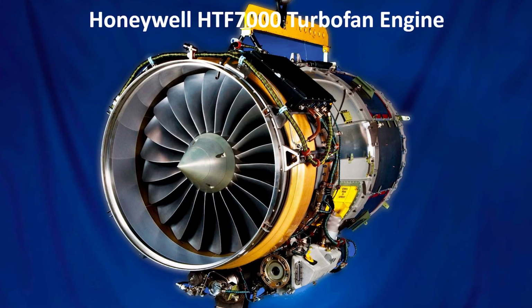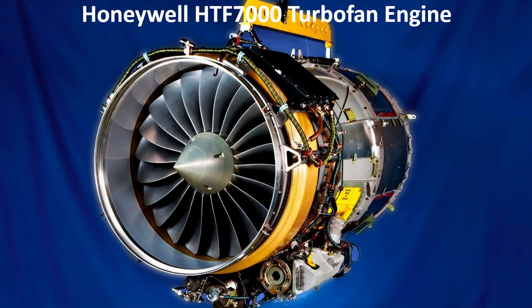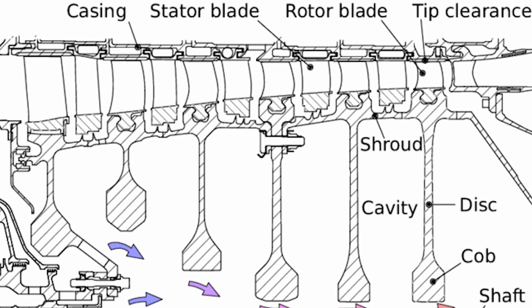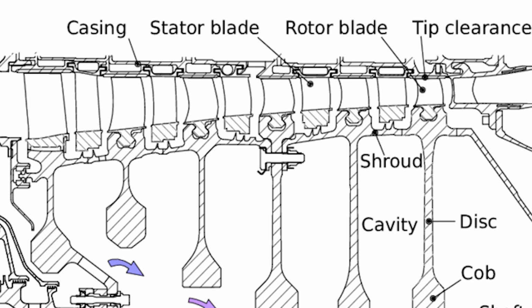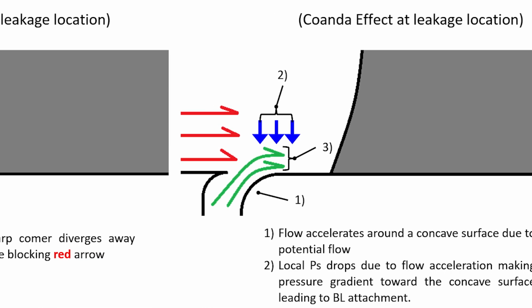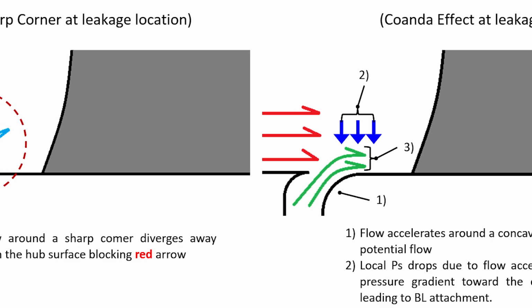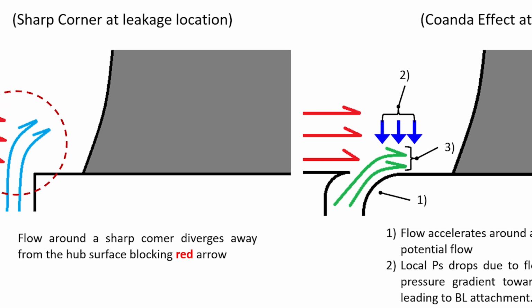Typical turbofan compressors are not perfectly efficient. Pressurizing the high-speed flow often results in air that leaks in different parts of the compressor. For a Honeywell Aerospace turbofan engine, the leakage flow is redirected into a hub cavity between two stator blade arrays. The current design injects air normal to the main flow path, causing irregular pressure gradients downstream, reducing stall margin and